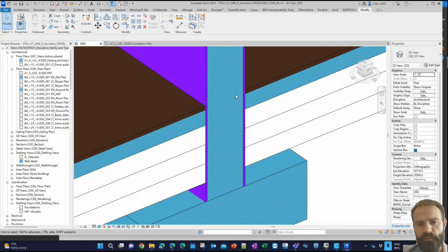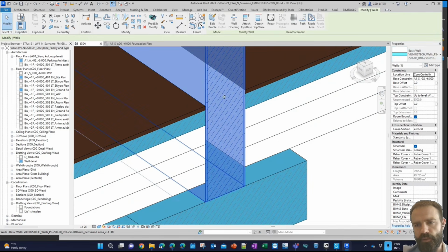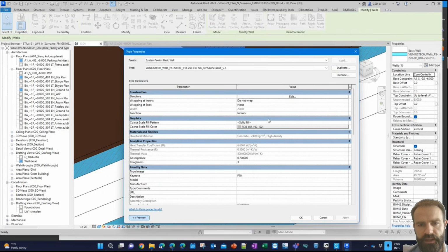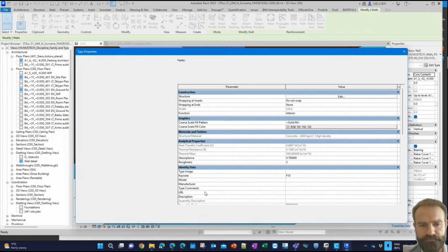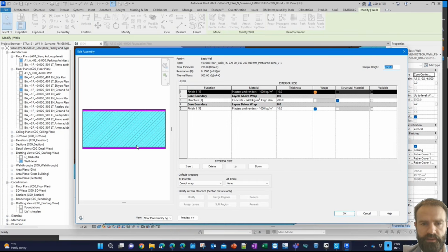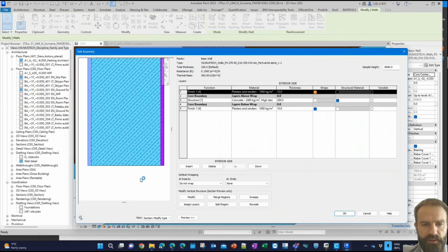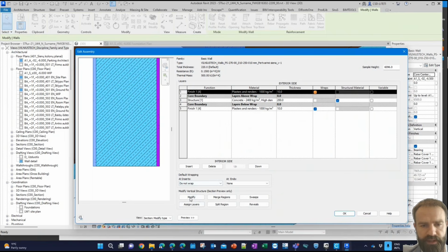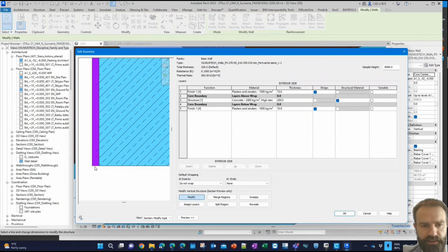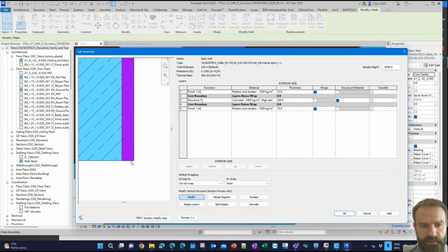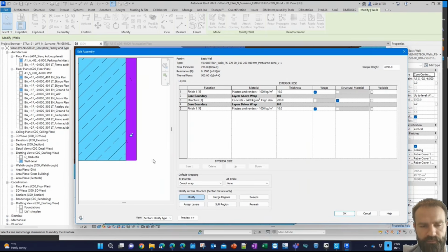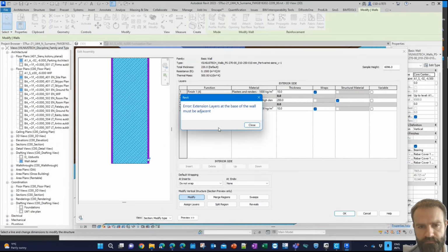And the last option, we can modify wall construction by going edit and selecting edit. And in here we select section, modify type attributes. And in here we go down and click modify. And in here we can select these elements and uncheck the lock and click OK.